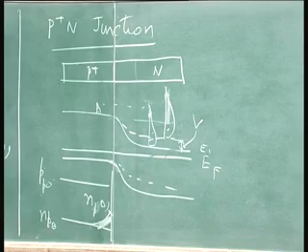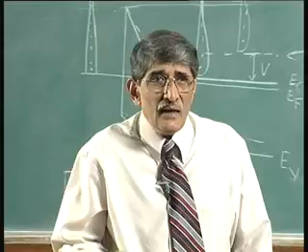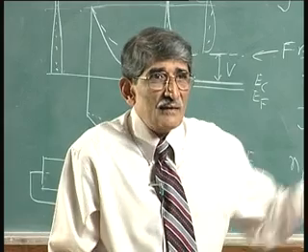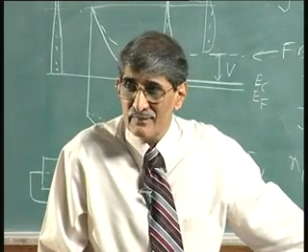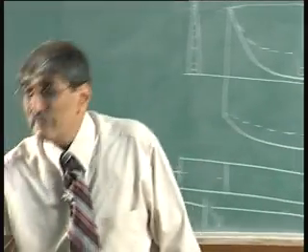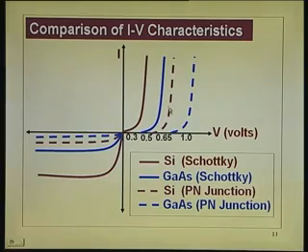So, these are the two subtle differences between the two, and for a given voltage the current there is smaller, because the current is ultimately decided by diffusion. That is the reason why physically this current in the p-n junction is smaller compared to this current which would have gone all the way up there. Or for a given current, you can drive a particular current with a smaller voltage with the Schottky barrier compared to that. That is actually the key thing.